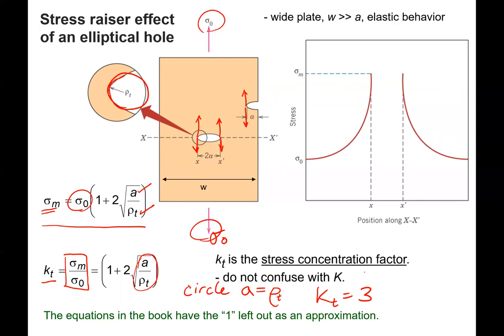All right, let me say a couple other things. This value A for the crack length, just notice by definition, A is the crack length if it's at the surface. If it's an internal crack, the internal crack length is 2A. Okay, so if a problem says that you have an internal crack of 1 millimeter, just write this down. So let's say you have an internal crack of 1 millimeter, then your A in this case is 0.5 millimeters.